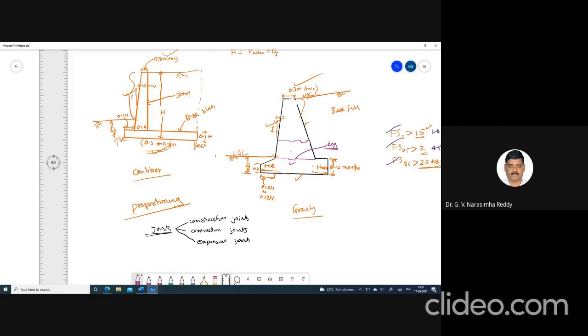Even for footings, generally you will lay the footing one day, and afterwards you will start constructing the column. Just before constructing the column portion, when you are laying the footing, we place some wooden plank so that you can provide a key, so that there will be a good joint between the footing and the column, even for a residential building. Those who have worked on site might have seen this. This is one way of construction joint. These are called keys.